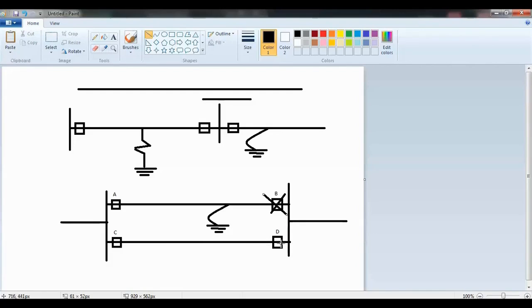Okay, in this scenario, you were seeing reverse with full forward. How will you delay the reclose and delay the carrier send while the fault is within your line, right? If I'm not mistaken, you said there's no problem. Why is there no problem? Because when this breaker saw the fault, it saw it as zone 1 within its line, so zone 1 will trip. But the fault was in this area.